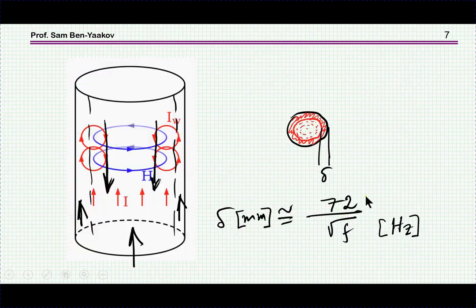The skin effect is something very similar, except it's not an interaction between two wires, but rather the interaction of the wire on itself. So if we have a current going in this direction, then we are going to invoke the magnetic field, which in turn will cause eddy current. And now what we can see is that on this end here and here, these currents are being added to the current going this way, and in the middle it's being subtracted, here and here, from this current.